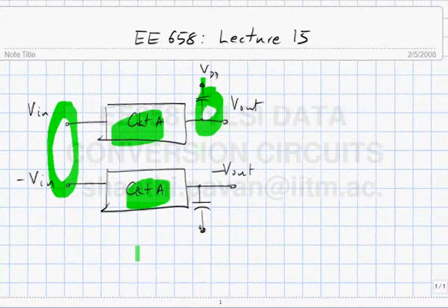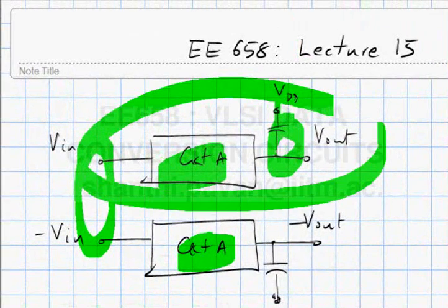cancelled out. So you can have, for example, a sensitive analog circuit operating on the same chip as a digital state machine, and the digital state machine is going to be switching at high speeds, causing lots of spikes on the supply. If one just used a single-ended circuit, so this is what is called a single-ended circuit because the signals of interest are the absolute node voltages, if I did something like that and VDD was noisy, then we see that the output will be your intended output